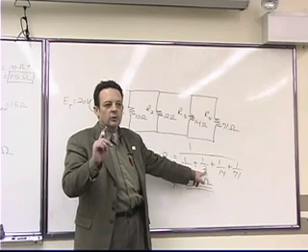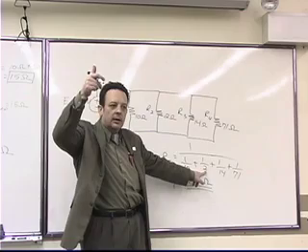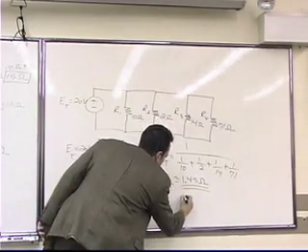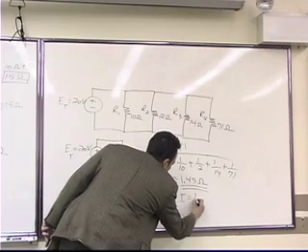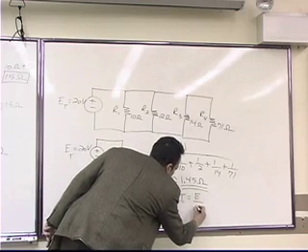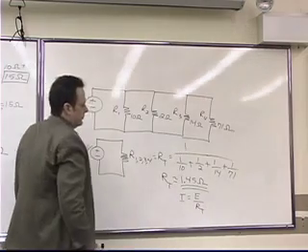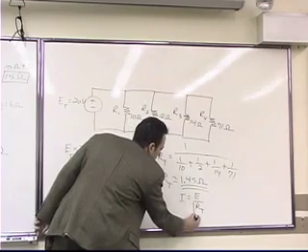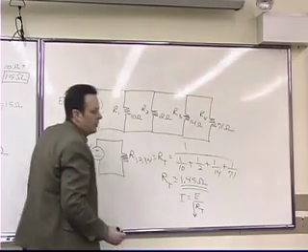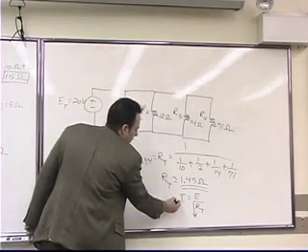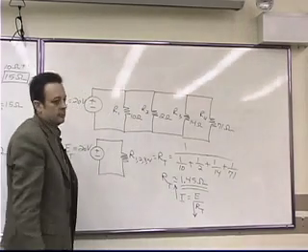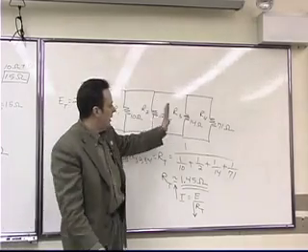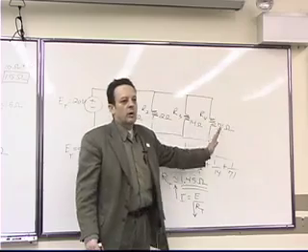That also goes along with why the current gets big. Because current is equal to voltage divided by total resistance. As the total resistance becomes a smaller number, what happens to the current? It becomes a bigger number. So in parallel circuits, every time you add another hairdryer, you draw more current.